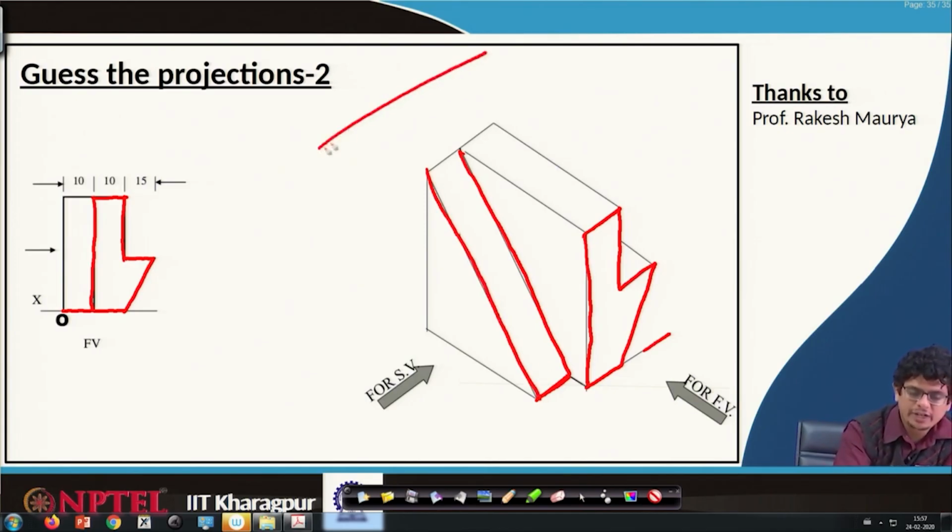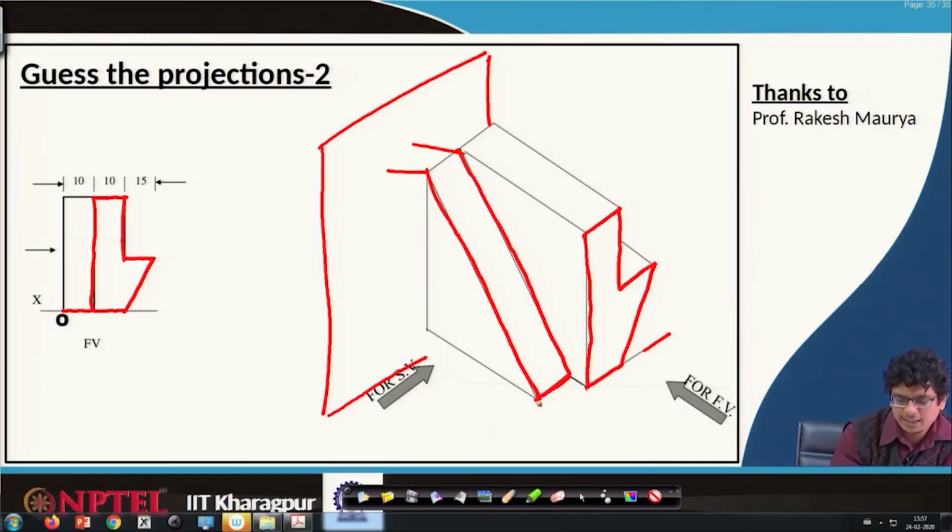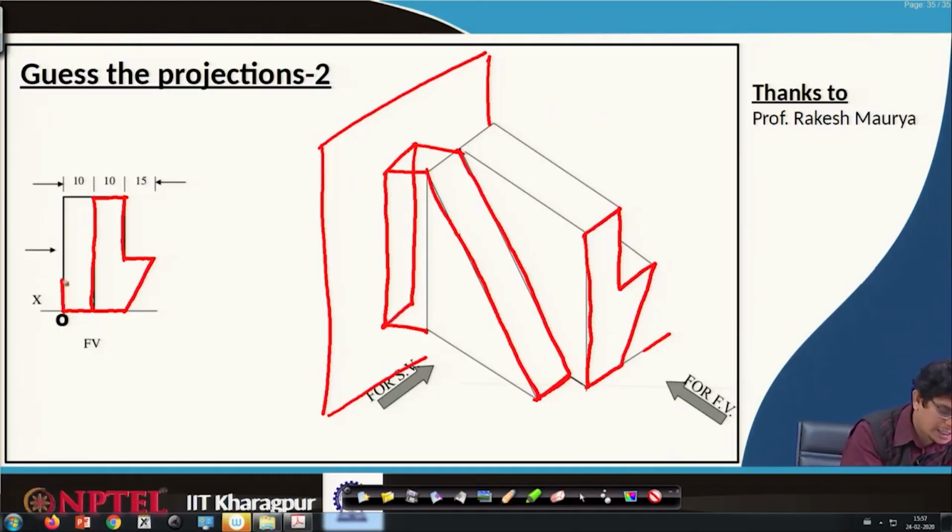we are observing it on this plane. So, this point projected there, this point also projected there, and this entire line points will be projected from there. That means, we will see it something like vertical lines. So, those vertical lines are these. This is the way we observe the front view of that object.